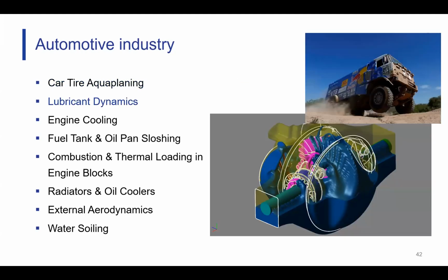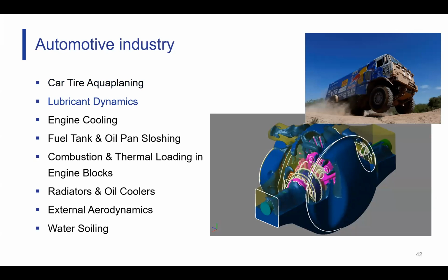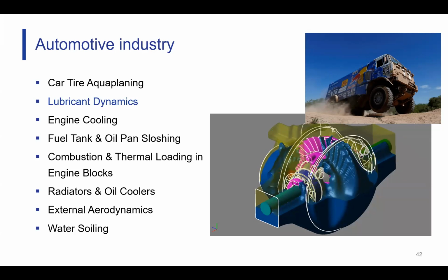Lubricant dynamics. So here we have lubrication of a differential. We have a full assembly that's been imported into FlowVision, with rotating components. We're going to be using the gap model on the gear teeth. So that's all these small spaces that are dynamically changing. And again, to top it all off, multiphase interaction. So in many CFD programs, this kind of geometry and motion, honestly, would be a nightmare. In FlowVision, this very much is a matter of just ticking the right boxes. That's it.